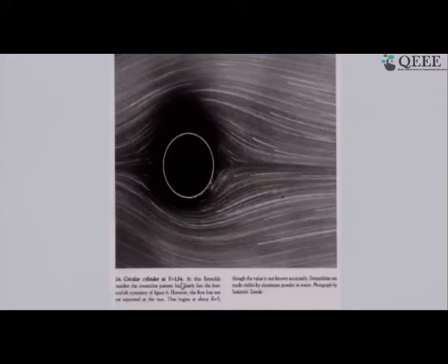Very small increase, very small Reynolds number, but see what has happened now. Here the cylinder is there, and the front part it's going like this, but now the back part, the wake has become even bigger, and there is a portion here where the fluid, you can see this fluid has come like this, gone there, and then gone off over there. So what happened over here? Well, the fluid which was here is sort of stagnant fluid over there. Nothing is happening to it.